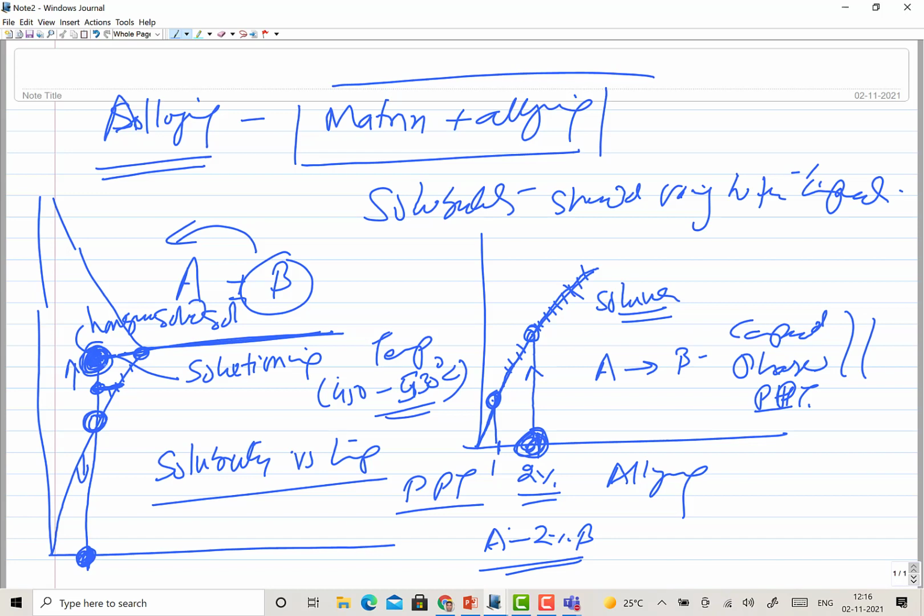Thereafter, what we do is quench it rapidly. Okay, second step, quenching. The alloying element which had formed a homogeneous solid solution at a high temperature, when it is quenched, everything is retained wherever it is present. So there is no time for diffusion to take place, and that is what leads to the formation of a supersaturated solid solution, because you are forcefully putting the alloying elements in the matrix by not giving enough time for diffusion to take place. So it forms a supersaturated solid solution.